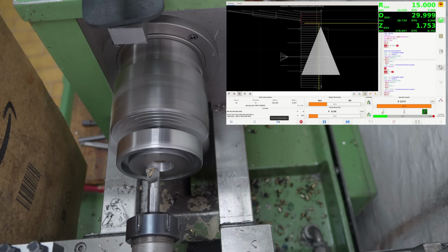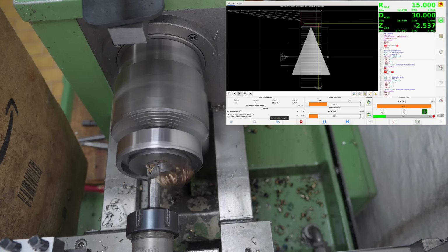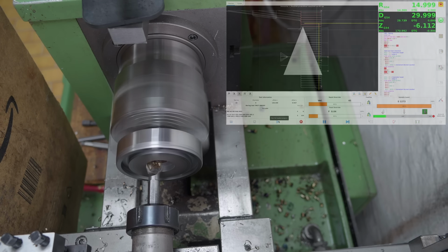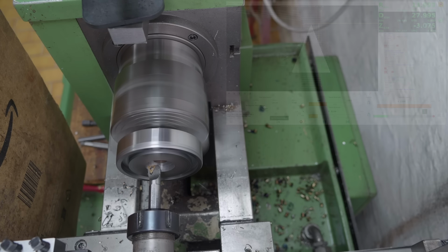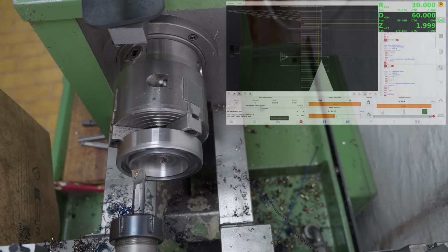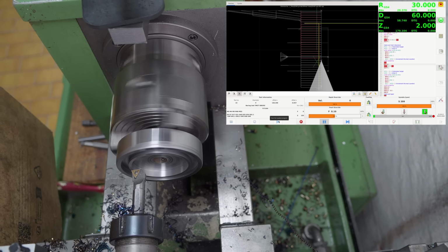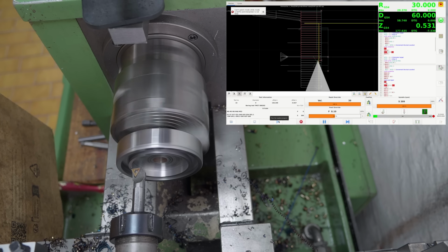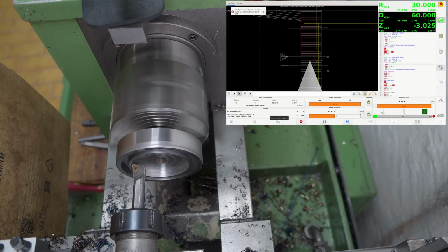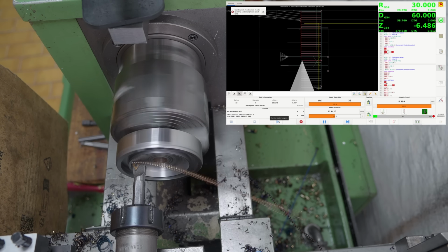We must be approaching a CVT bump somewhere around here. As the radius increased and I dropped down to the lowest ratio on the CVT and then the lowest frequency available, there was almost no torque left, so I did a manual stop and put it in back gear. I was also having some issues with the automatic switching of back gear at that point, so I also did this with just the G97 constant RPM mode, so all of the next cuts were done at 200 RPM.